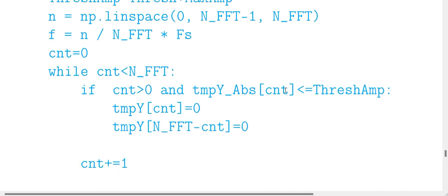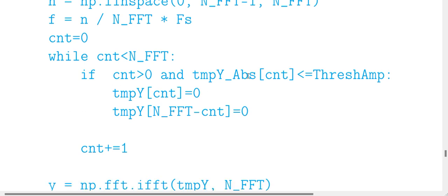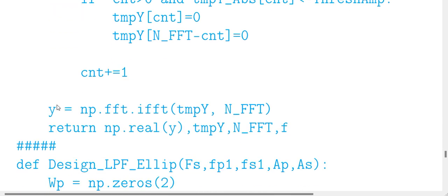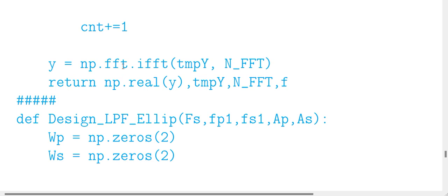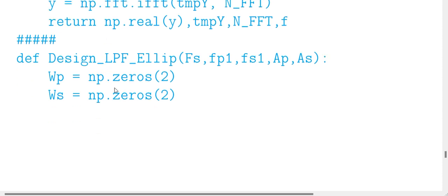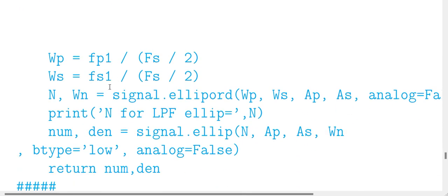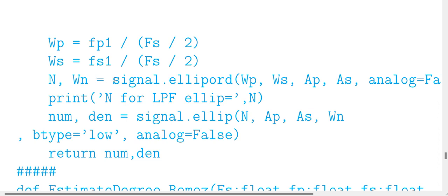Here you see how we have made the thresholding: if the amplitude is less than a number, put it as 0, and of course the complex conjugate, and it filters out. You know, white noise occupies all frequency components, so in total we should have problems with it. It's impossible to remove the Gaussian noise 100%.